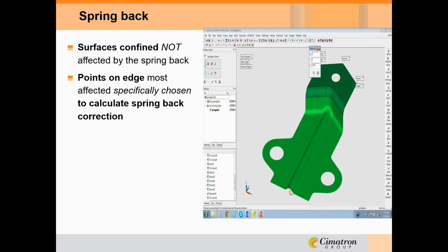And this is a manual adjustment. We're touching those 3 points, letting that entire area flex. That would accomplish what we're dealing with in the springback. So maybe I'm okay with that. Maybe with a simple part, that's all I need to do to adjust for springback. What if I need more accurate solution? What about more points or tougher geometry? Again, I got to stress to you, this is an example of gathering information so that we can correct the model and make the changes.